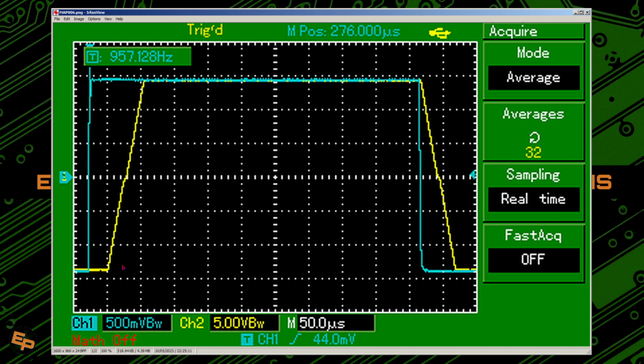And this can definitely be a problem in certain circumstances, in certain circuits. This delay is basically caused by the saturation of some transistors inside the op-amp. So this is definitely something we need to be aware of, and in some cases we need to do various tricks to our circuits to prevent this from happening. Otherwise we might have undesired effects going on in our circuit, and overall it will not work as expected.